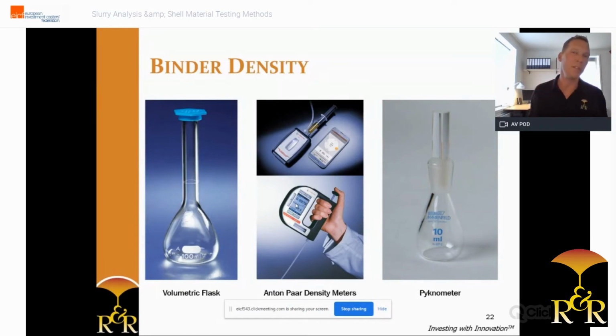If you do decide to use the volumetric flask like the pycnometer, I recommend to have enough available to cover each sample. Otherwise, the operator has to clean and dry the flask in between measurements. It's a hassle. You don't want that.